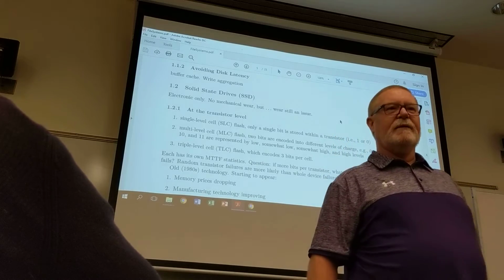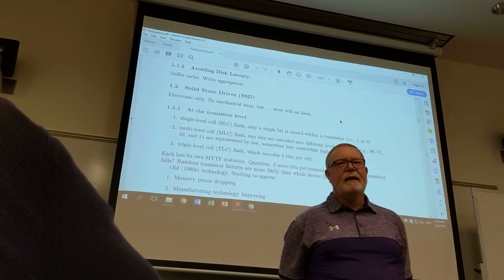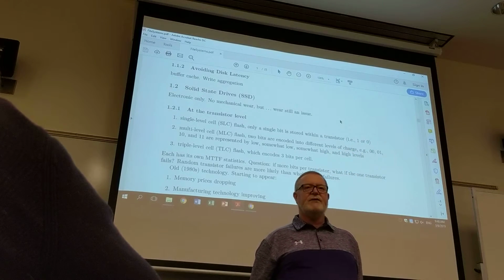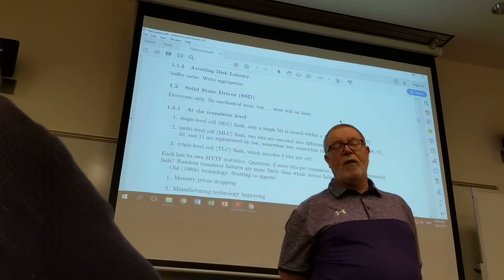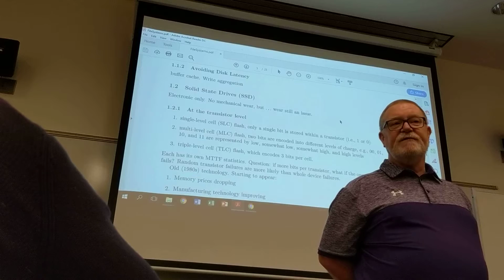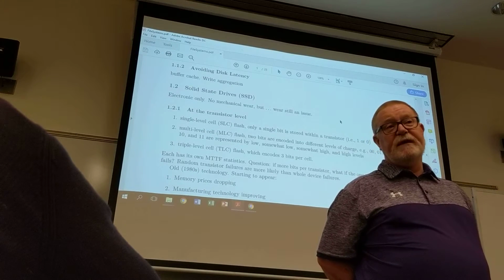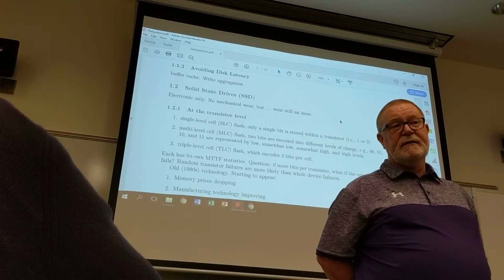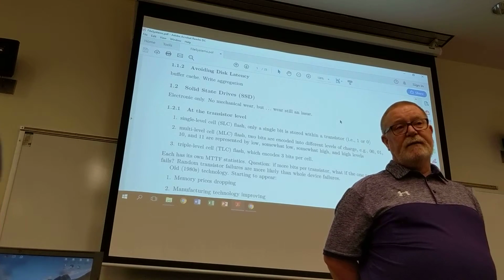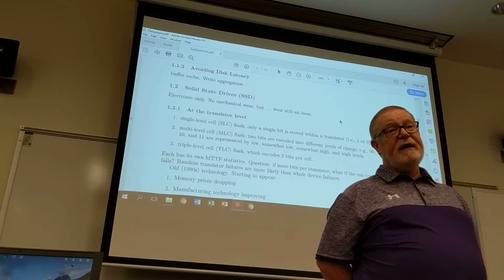Would that mean that bigger drives would last longer because you have more space to spread? That's the theory. The theory is that if you're doing wear leveling, the more tracks you have, the less you visit each track, and therefore the less you visit each bit, so you improve the mean time to failure of your device. And that is a big factor.